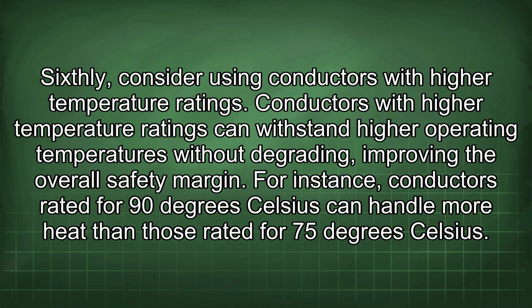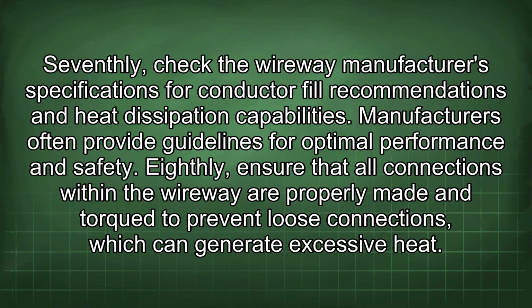Sixthly, consider using conductors with higher temperature ratings. Conductors with higher temperature ratings can withstand higher operating temperatures without degrading, improving the overall safety margin. For instance, conductors rated for 90 degrees Celsius can handle more heat than those rated for 75 degrees Celsius. Seventhly, check the wireway manufacturer's specifications for conductor fill recommendations and heat dissipation capabilities. Manufacturers often provide guidelines for optimal performance and safety.